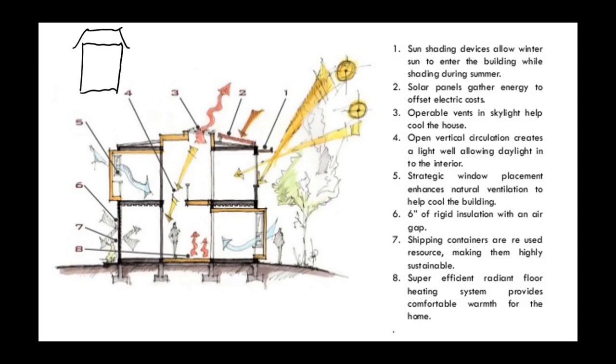And if you remember, we had a neutral line through the house, and when we talk about the balance or the stack effect, we had this cold, cool air being drawn in from the bottom through gaps in windows and doors, in fireplaces, and so on and so forth. And then that ultimately went out in various directions through the top of the house, through the roof, and this was called the stack effect.